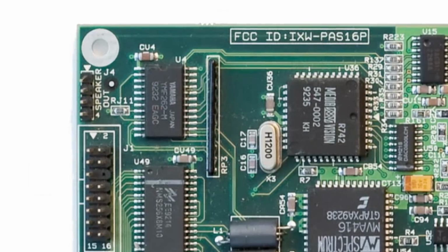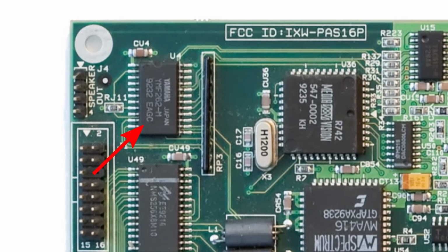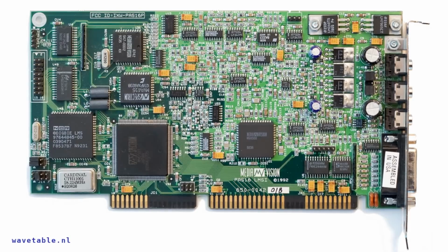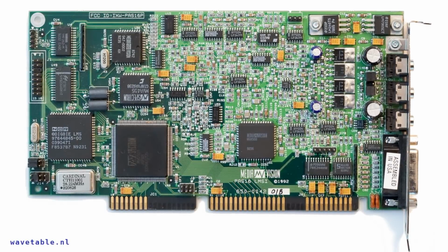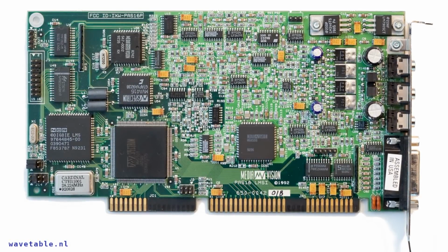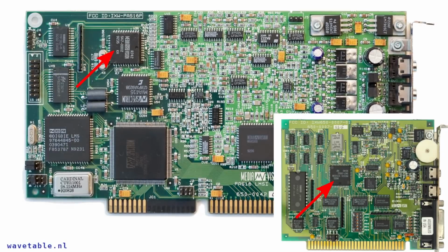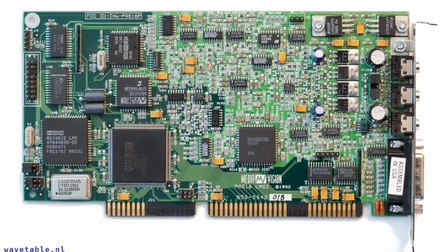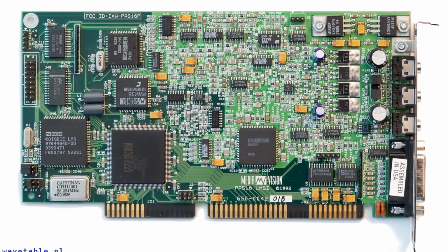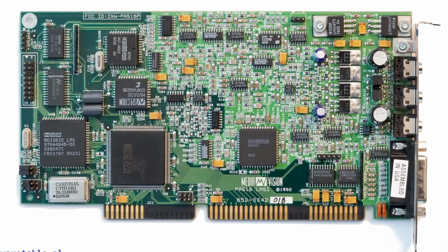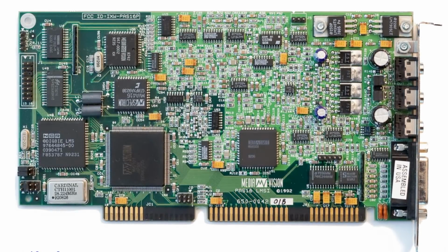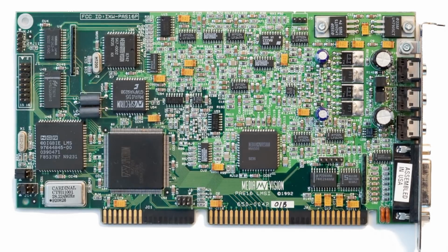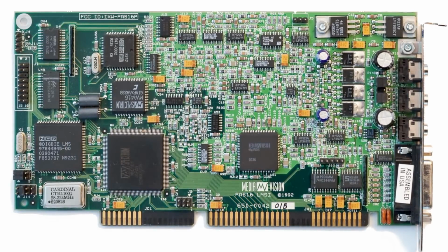Pro Audio Spectrum 16 made the switch to OPL3 as well, just as Creative did on the Sound Blaster Pro 2. And this time, MediaVision didn't make the same mistake again and integrated the Sound Blaster compatibility by reusing the Thunder chip from the previously developed Thunder board. Unfortunately, MediaVision didn't have enough time to go one step ahead to implement the Sound Blaster Pro 2 compatibility as well. Maybe they were too confident with their own stereo capabilities from Pro Audio Spectrum and thought that the game developers will continue to support their products in the games.